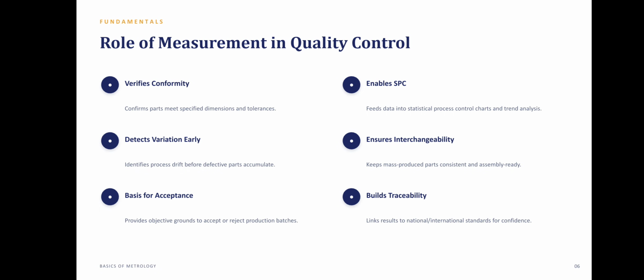Coming to the next, role of measurement in quality control. It verifies conformity, detects variation early, provides basis for acceptance, enables SPC, ensures interchangeability, and builds traceability.